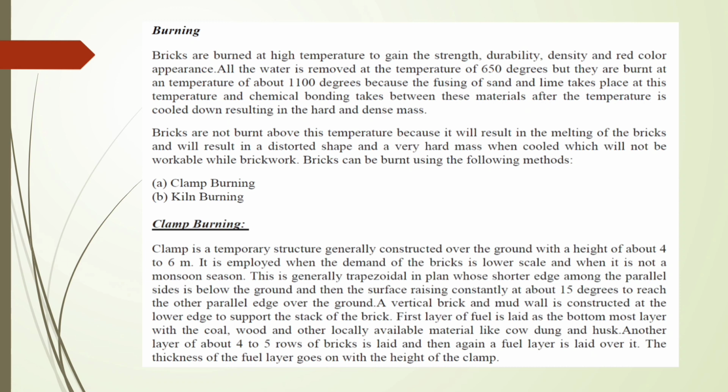Bricks are not burnt above this temperature because it will result in the melting of the bricks and will result in a distorted shape and a very hard mass when cooled, which will not be workable. Bricks can be burnt using the following methods: clamp burning and kiln burning.